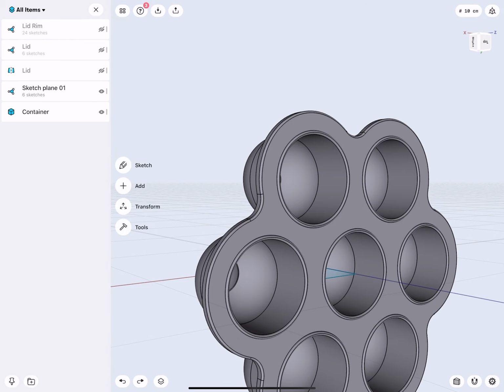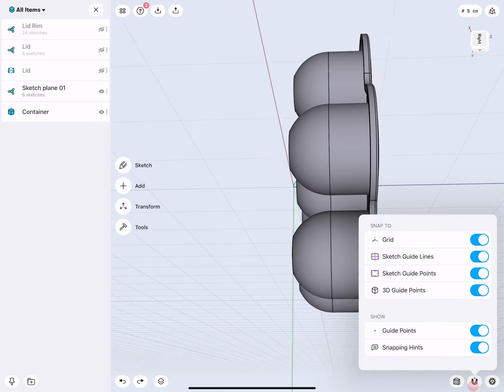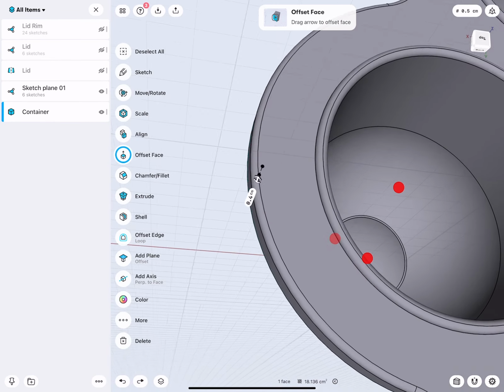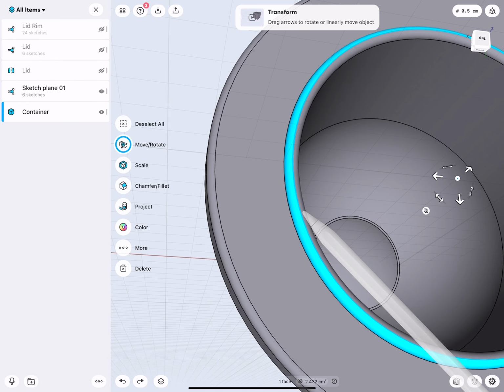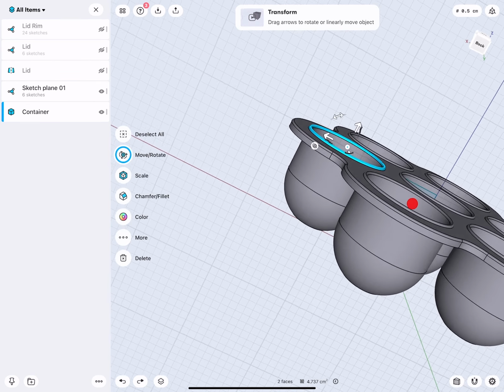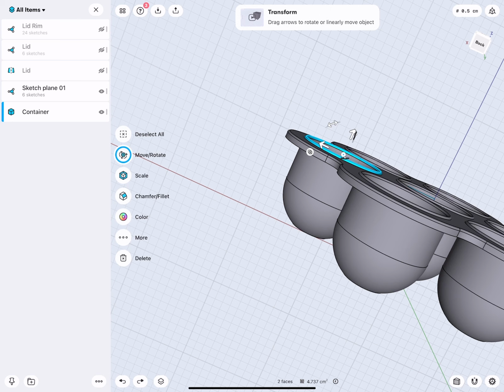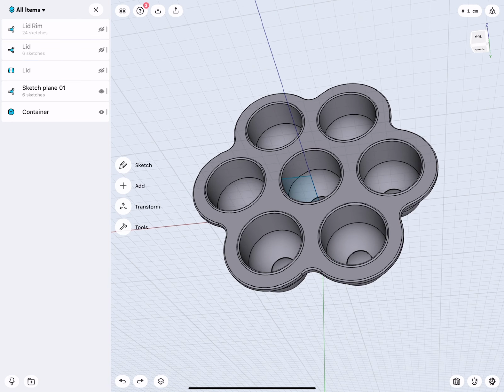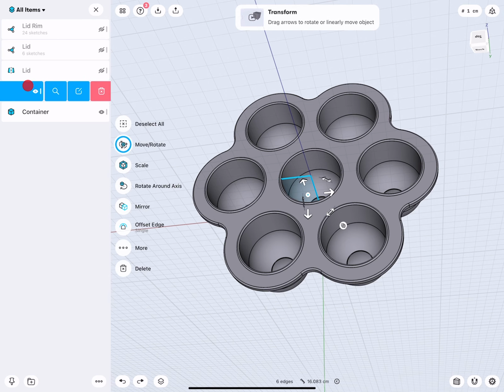And now we have to build a lid, and the lid should sit on top, go around, have elements that snap on the back, and then we need also to have grooves cut out so that this goes into the cavities, so we can create some sort of a seal. How do we do this? Sounds very complicated, but again, it is very easy if you just think step by step, logically, how can we create everything out of easy steps. Work smart, not hard. So let's take a look at our sketches and clean everything up.